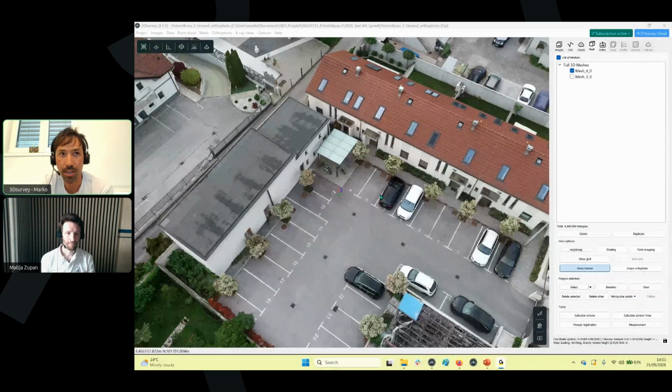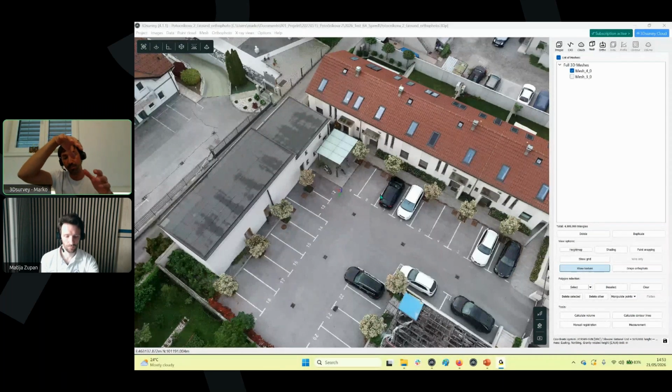We already recorded a webinar on how to do this in the past. What's important here is, if you would like to combine drone photos with photos taken from, I don't know, a person's perspective, you need to get these perspectives pretty close. So if you map perpendicular down, 90 degrees nadir, and then in a horizontal way, this is too much for the algorithm.